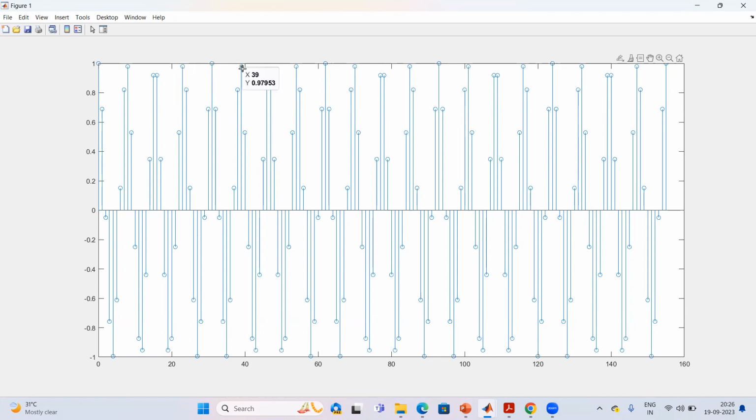Here you can see again, if you add on, you will get the same samples of the same magnitude. But the problem is that it is not valid for all other samples. Some samples look like they have a different periodicity, but you cannot say that it is periodic, because here and here it is periodic. These two samples have the same period of 31 samples. From here to here it will be 31 samples. For the other samples, this periodicity is not equal to 15 or 16, and therefore the actual periodicity is 31. You can verify that from this graph itself.